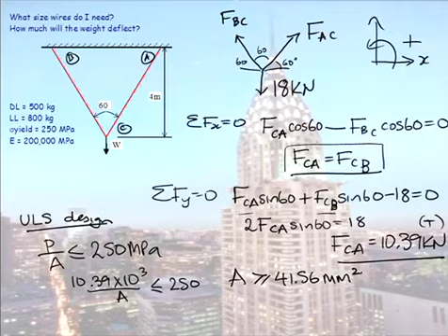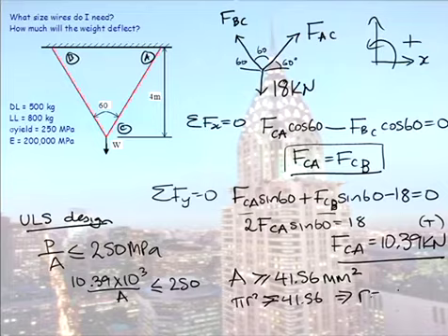It is a rod section, so this is my pi r squared. So now I'm just making it effectively equal to that. And thus from that, r is equal to 3.63 millimetres. Now this is where you can see some extra factor of safety, because you're not going to go into the shop now and say, I want some rods that have a radius of 3.63 mil, because they're going to say, well, the nearest thing we've got to that is 4 mil or 3.8 mil. So most of the time you'll be putting in something slightly bigger because of availability.